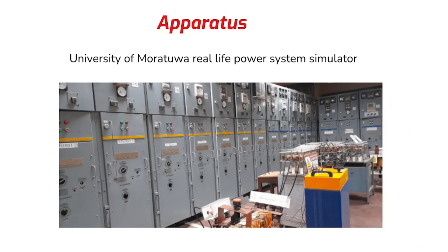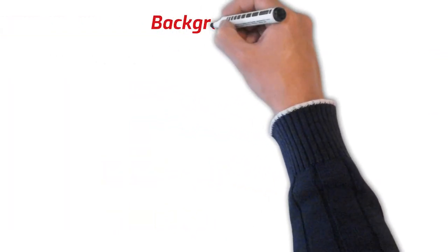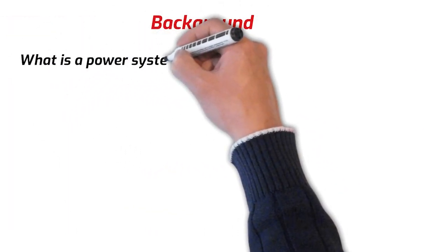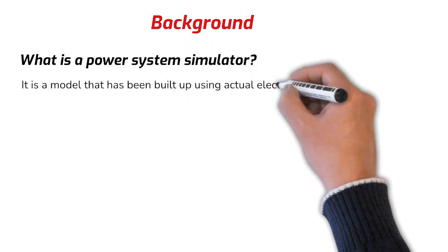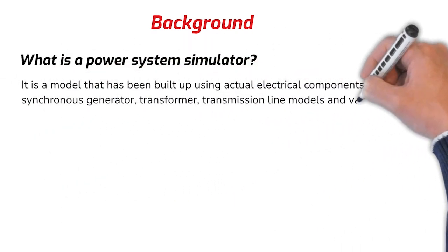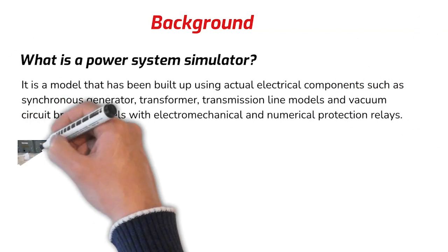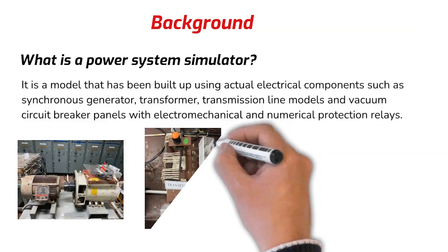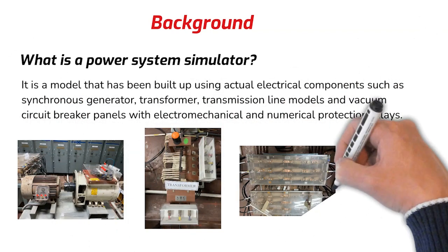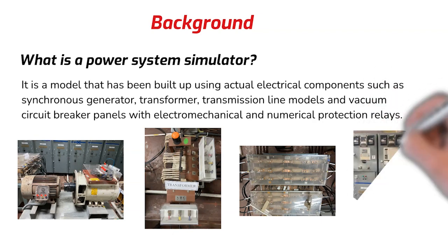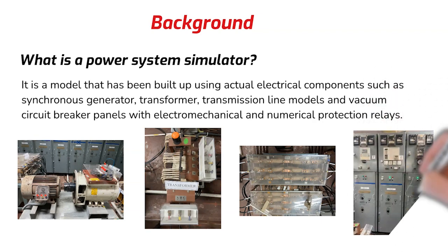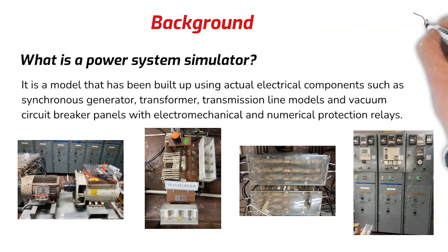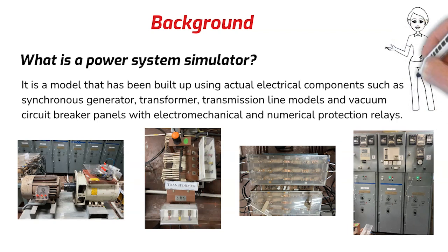Power Systems Lab. First, let us learn what a power system simulator is. It's a model that has been built up using actual electrical components such as synchronous generator, transformer, transmission line models, and vacuum circuit breaker panels with electromechanical and numerical protection relays. This voltage scaled down version of the actual system is expected to fulfill the requirement, providing a practical exposure to